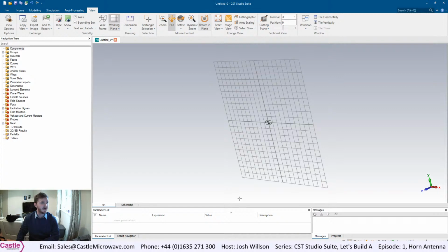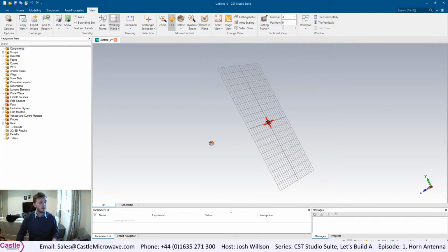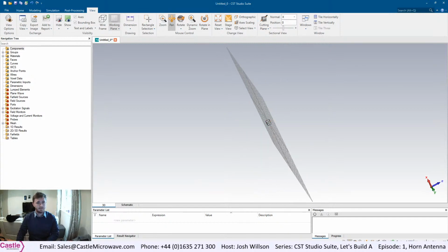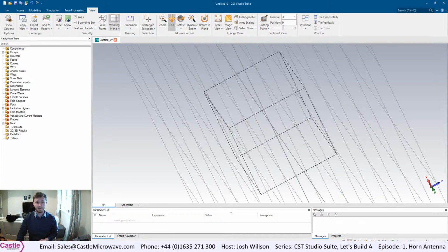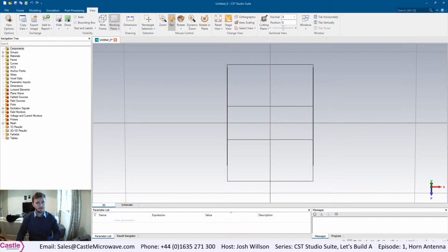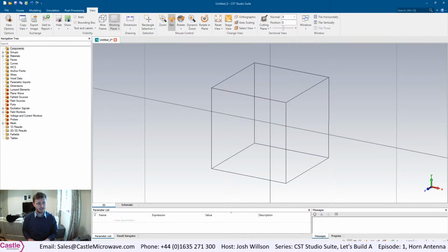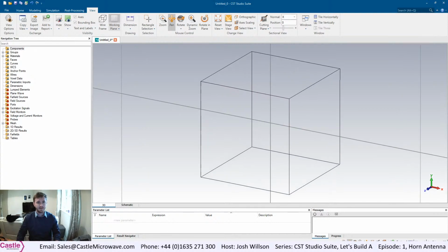If I have it set to pan, I can then use Control to rotate around and Shift to rotate in the plane. You can also use spacebar to restore fit to view, and 0 through 9 provide some default alternative views. We use 0 to go back to standard isometric and space to fit. Let's return to the Modelling tab.